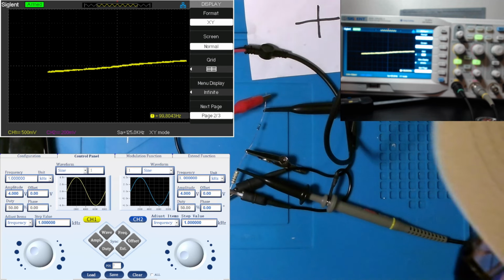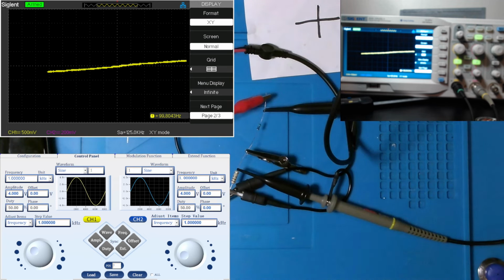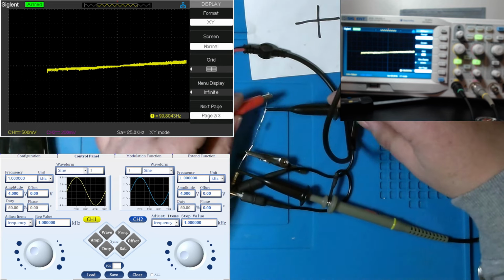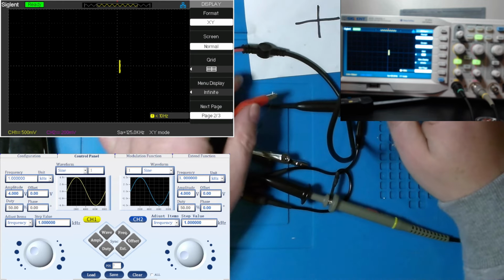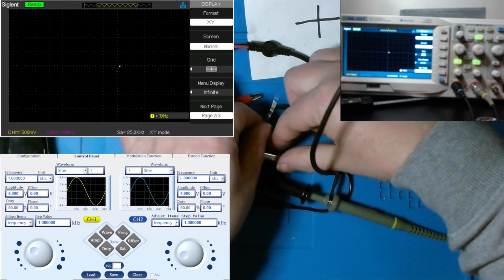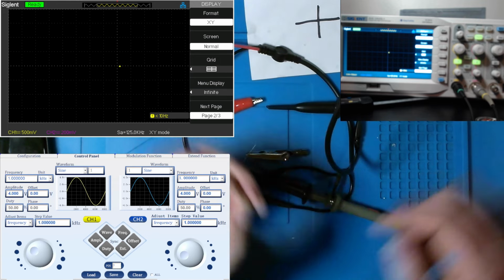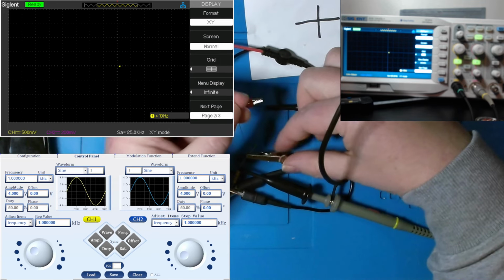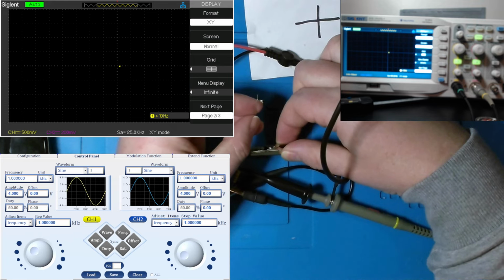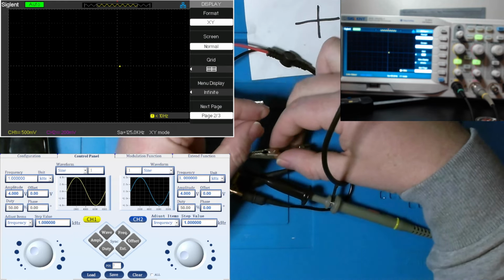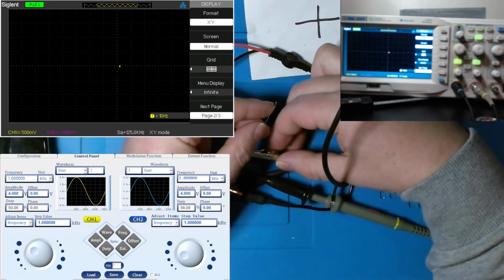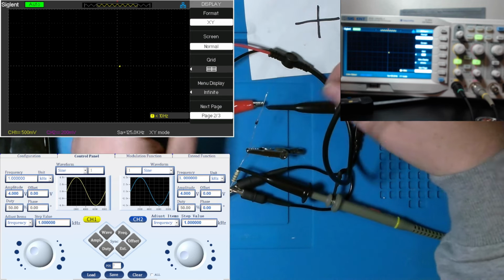I went ahead and pre-pulled out a couple of diodes. We'll first look at a 1N4148 switching diode. Let me decouple this and this guy right here and this guy right here. Make sure I orient my diode the correct way, cathode and anode. Alright, I think that's making a decent connection.